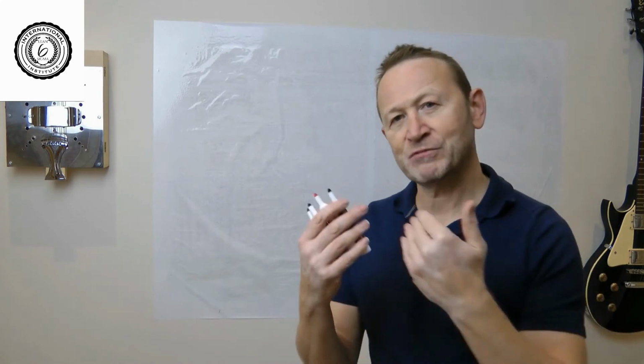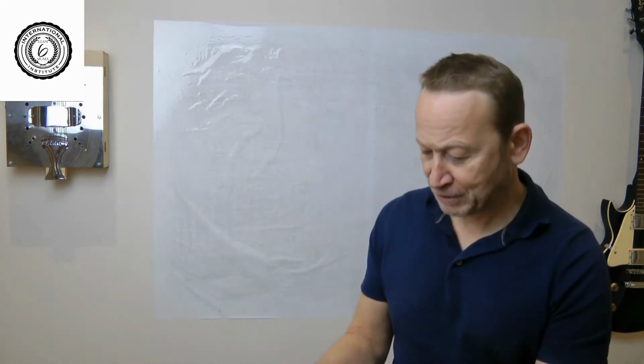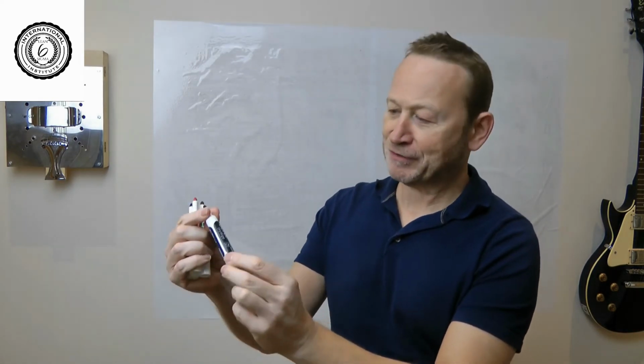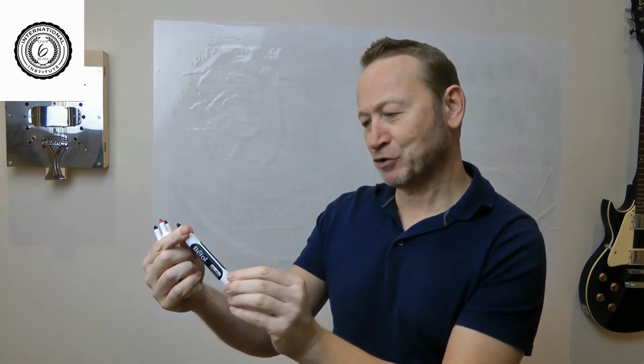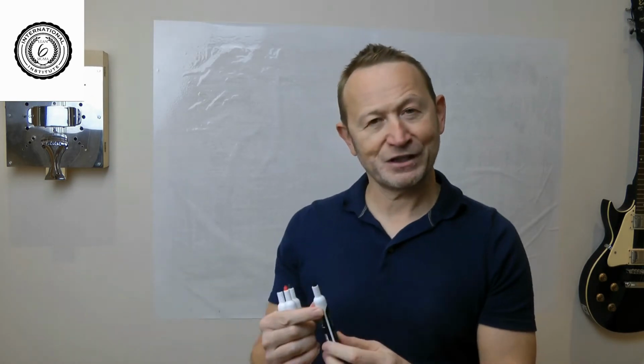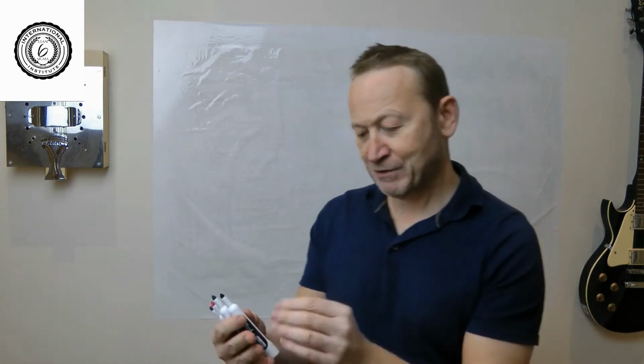The subject of today's newsletter, well, we're going to talk about MSA, but we're going to talk about MSA for attributes, for some kind of cosmetic inspection maybe. So let's imagine we were inspecting the quality of the print on my felt tip pens, and we were saying the print is of good enough quality, it's a pass. The print is defective, and someone's saying that has to go in the bin or be reworked or whatever. So it's not measurable. We're not measuring the diameter or the weight or something like that. We're inspecting the cosmetics, and of course it's either pass or it's fail. That's attribute data, and that's a different style of MSA to the MSA that we've talked about previously.